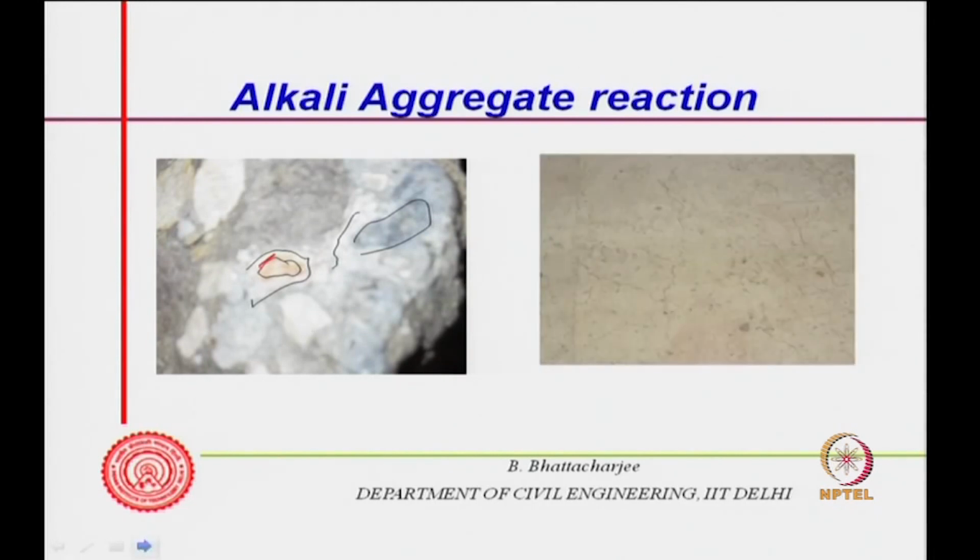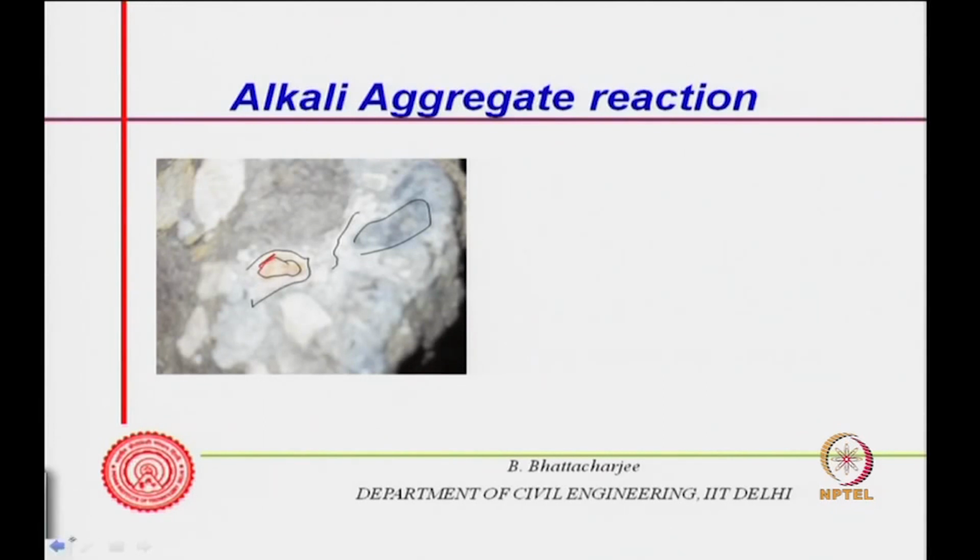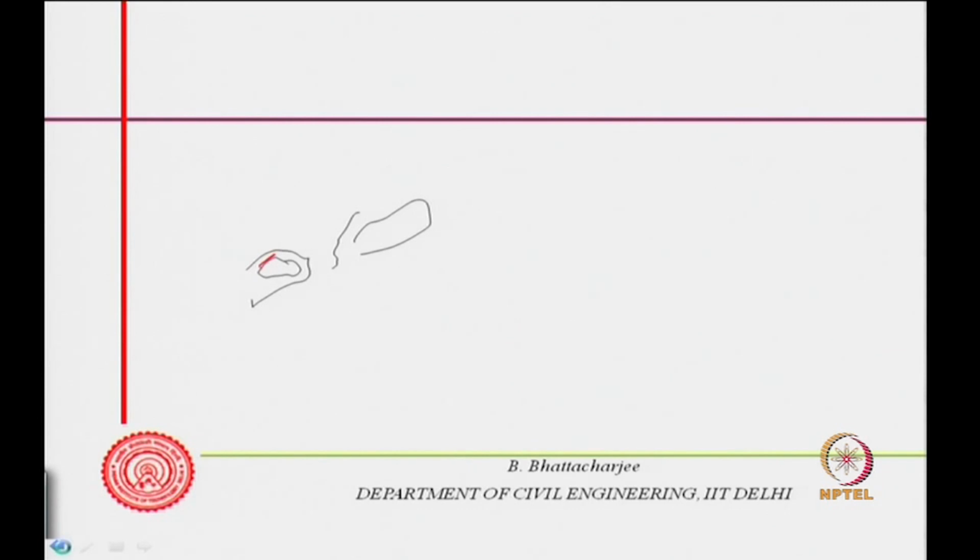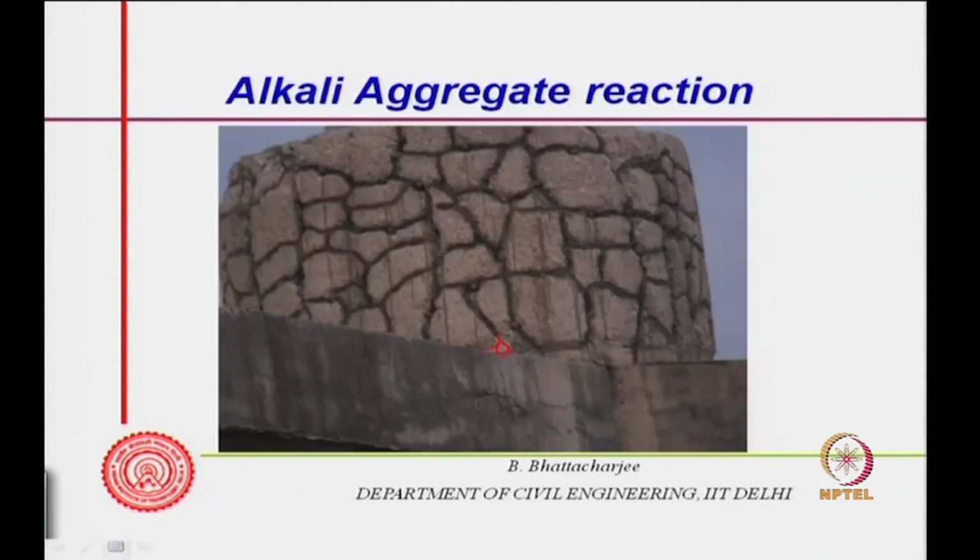In early stages, you might see fine cracks of this kind, and in later stages this will result in formation of a complete crack all around the places, and the structure will disintegrate. Remember, this does not occur in the beginning; it takes at least 5-10 years. In India, Hirakud dam is an example that faced this problem.